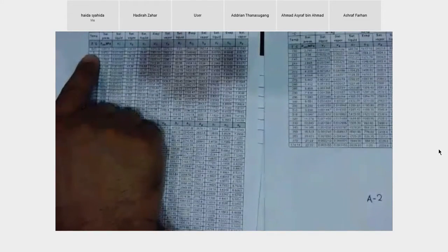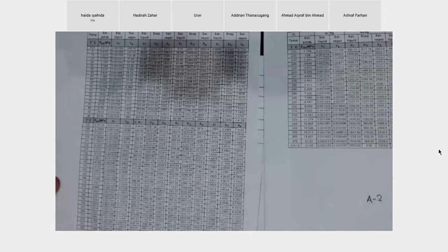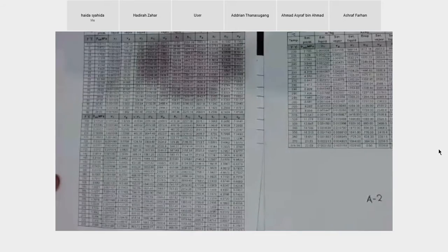So if you look into table A1 and A2, okay, A1 first. So the A1 is that the water starts from 0.01 degrees Celsius, 5, 10, sampai lah until 374.14. That's what we learned during SPM, or mungkin the Arab people probably in their country they call it O level. Okay, so we say that the saturated water, the hot boiling water, is 100 degrees Celsius. So while learning thermodynamics, the hot boiling water at 100 degrees Celsius is not true.